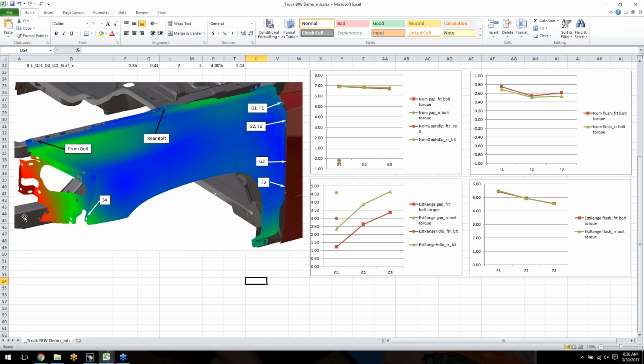And then once the fender is brought in, the bolts are going to be put into this hole here, and there's one here, and a couple of them here, and one behind inside there. Driving those bolts may deform the fender and twist it, so it may affect the gap and flush measurements here. I also took a measurement on the surface here to see where this flange is going to end up. This flange is going to come in contact with the headlamp later on.